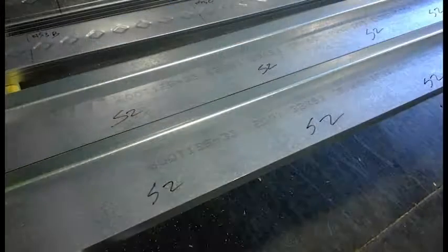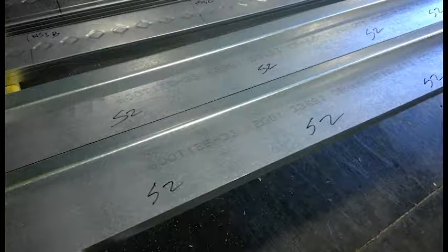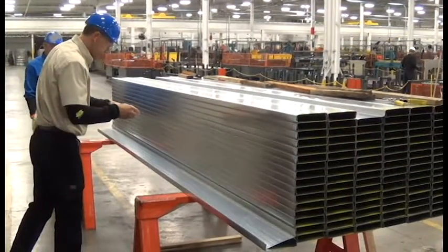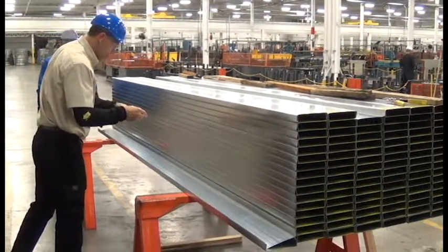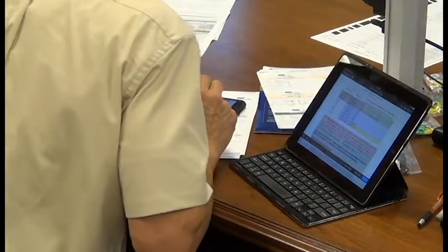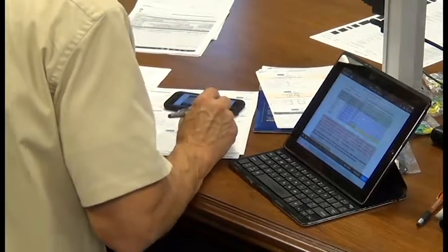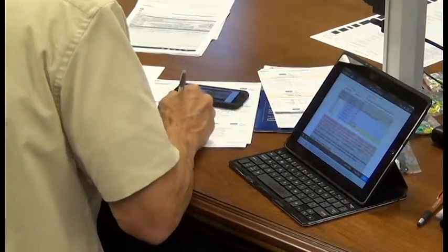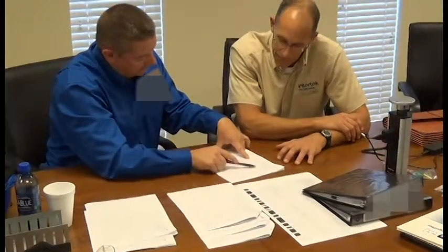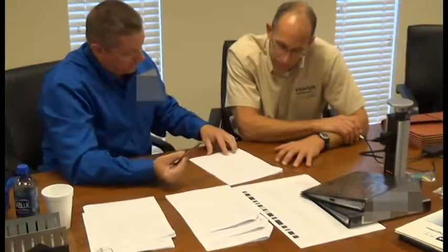The inkjet on the product will be checked and verified to match the product being sampled. Please note that the inspector should be taking photos of the full inkjet markings at this time because this data is critical. A photo eliminates potential typing or handwriting errors. Later, during the inspection, this inkjet information will be verified to the trace documentation, mill cert, or test results. A photo has saved many an error from being made.